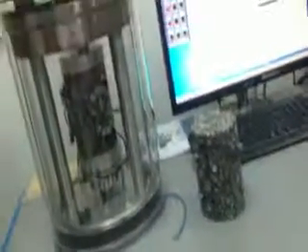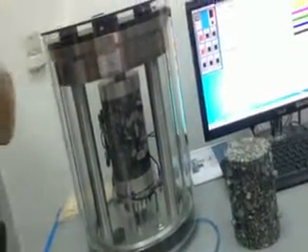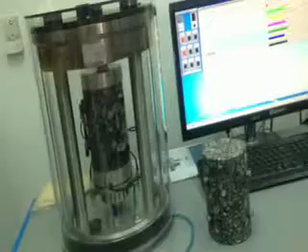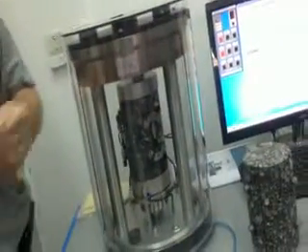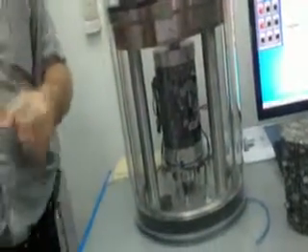Then the sensors are 0.038 and 0.054, that's okay. The software with these transducers, when the test first starts, will take a reference value as those current points. So you don't have to take it to zero. It'll use that initial point as a reference to give the net value.